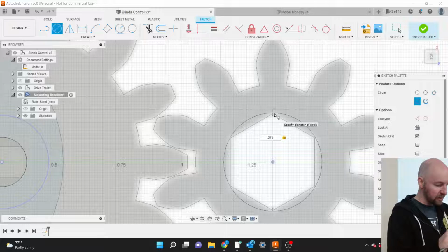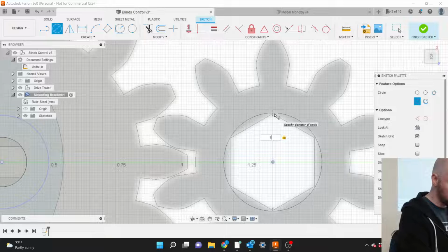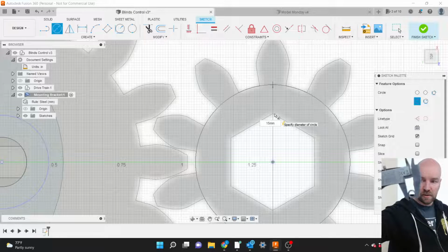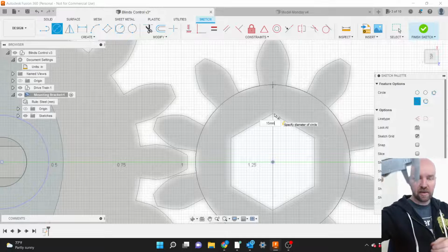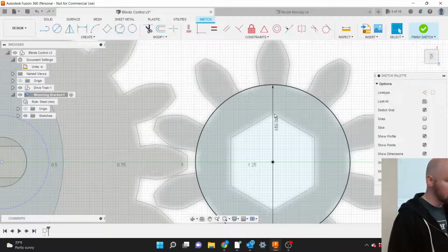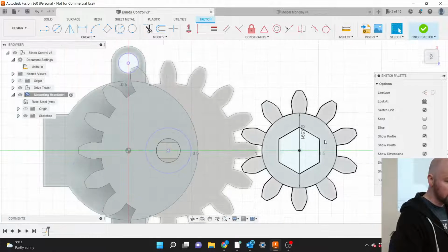And if you're putting a bearing in, I have these little bearings, and they are 15 millimeter outer diameter, so that is the circle you would need there. So again, mine have these bearings, so I'm going to put them at the 15 millimeters outer diameter there. Bless you. And that way, this little bearing I got, again, kind of overkill, but bearings are pretty cheap, so. All right, 15 millimeters is my bearing size there.